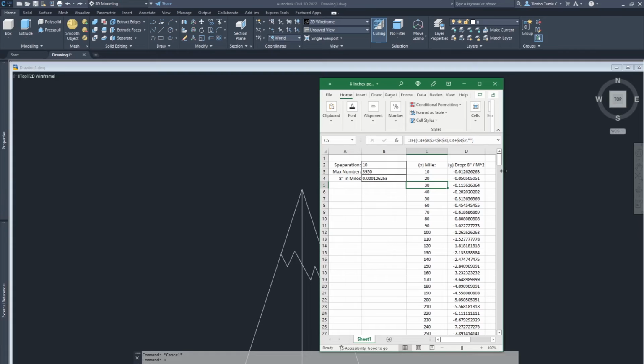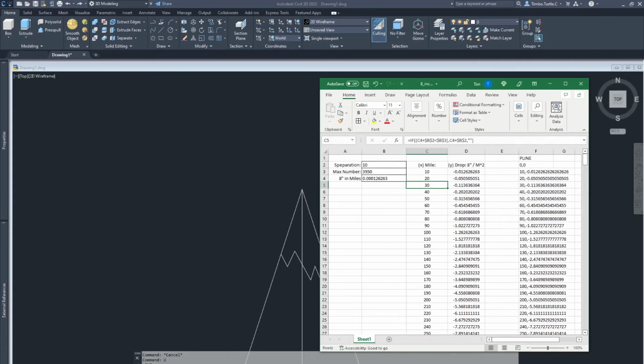So what I've done here is a little trick in AutoCAD. If you paste commands to the command line, it'll accept them, no matter where they come from. Now, you can use a thing called a script file, which is basically a text file with the commands in it, and you can load the script file. I could have written a little program to do this, but in this case, all I want to do is, rather than me manually typing in, I'll paste it into AutoCAD. So all this here is taking that line and that line and putting a comma in it so that it's the coordinate. Now the command I want to use is pline.